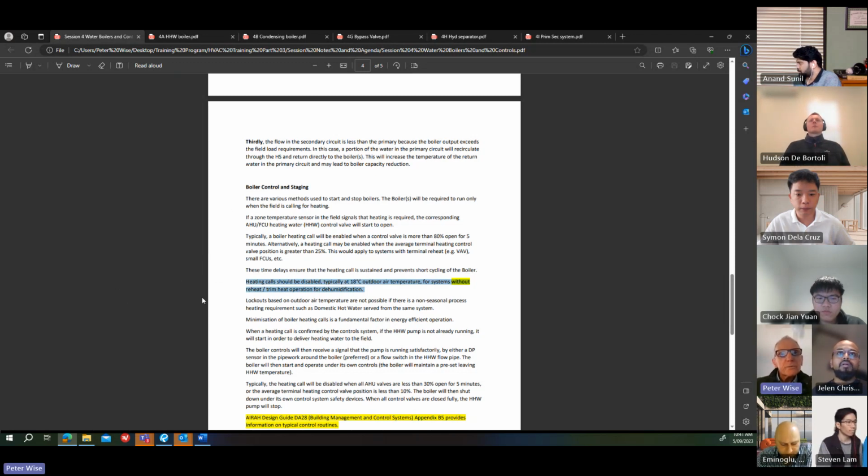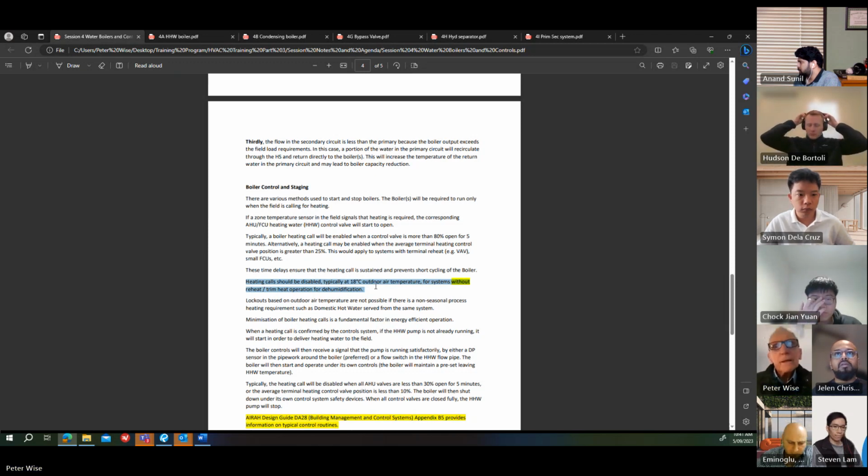Heating coils should be disabled typically around 18 degrees outdoor air temperature for systems without reheat or trim heat operation for dehumidification. Now this is in a situation where you don't have trim heating or reheating for dehumidification, obviously.